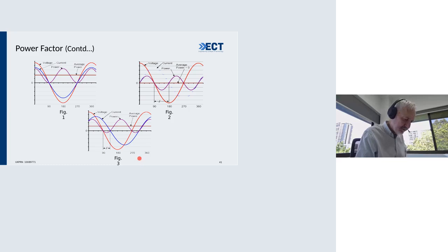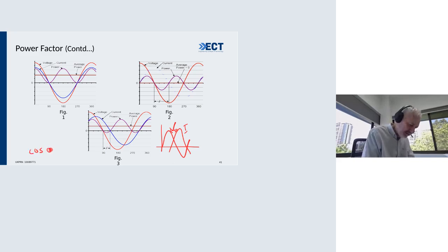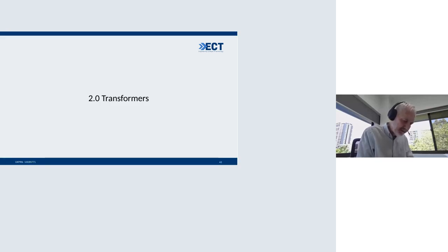Always a very interesting challenge when you're doing calculations there. And typically the big issue is that you've got an angle between your current and voltage. It's the distance between the current and voltage. So there's your voltage, current could be phase shifted, like that. And obviously there's an angle between them. That's your power factor. Obviously the trick is to get the power factor cosine phi equal to 1 if you can. Very hard to.